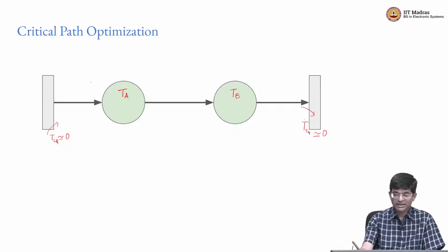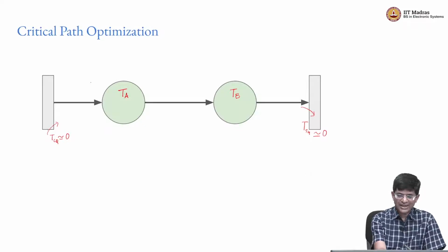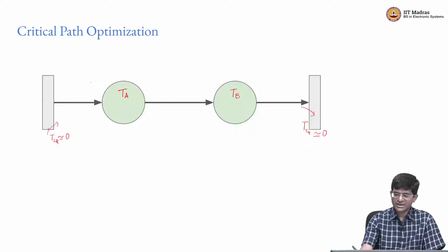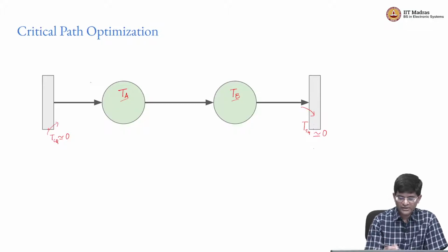Now as we know, there is also a third parameter called the hold time, but the hold time is more important when we are looking at whether the signal that comes out over here can race through this and get to this second flip-flop before the hold time has passed on that flip-flop. And as long as there is some finite delay TA and TB over here and some logic, that kind of hold violation is not really going to happen. So at least for this circuit and for finding the speed at which it can operate, I am going to ignore the idea of the hold time. And as I said, I am also assuming for now that the TCQ and T setup are negligible. Okay, so with all of that in mind, what can we say about the clock period that can be used on this circuit?